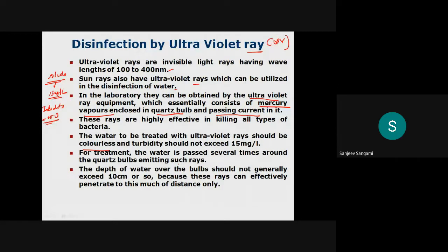Up to 20 NTU you can do it, but if it crosses 20 NTU, then it has to be reduced to 5 NTU. Better, 20 NTU itself is a maximum, but if you reduce to 5 NTU, then only it is possible to treat with ultraviolet rays.